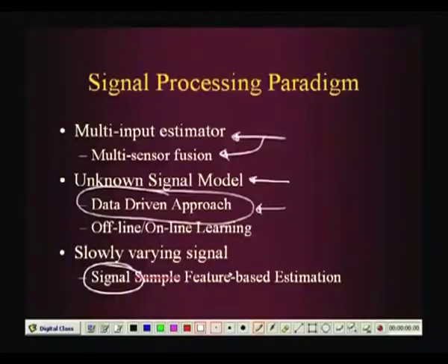We also found that in this case the signals are very fast varying, that is, you get signals from sample to sample at maybe 30 kilohertz, but the tool wear is actually a very slow process. So we should not set up a model based on signal sample values, because the wear between two signal sample values is going to be so low that it will be very difficult to estimate anything. So we thought that we will create the estimator in terms of the feature of a lobe.